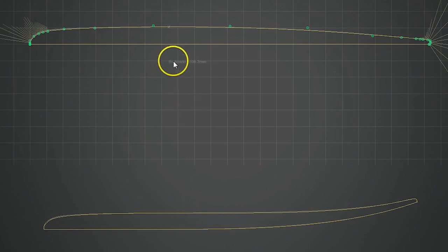And so here we are in the profile view. We edit the profile with the board with 0 rocker up here, so it's easier to measure the actual thickness off a baseline at 0, and then that's automatically transferred into the rocker version down below. This allows you to actually adjust the volume to where you want it to do exactly what you want.